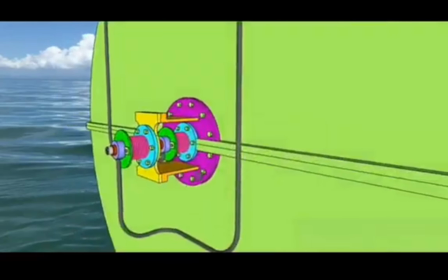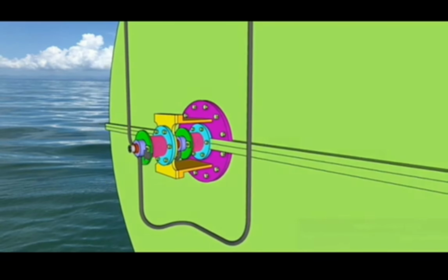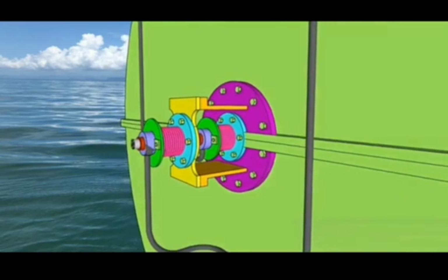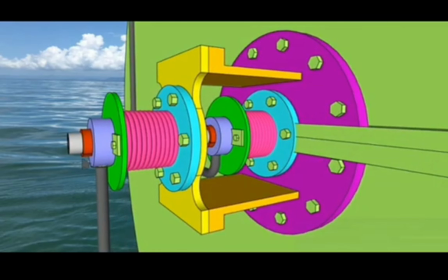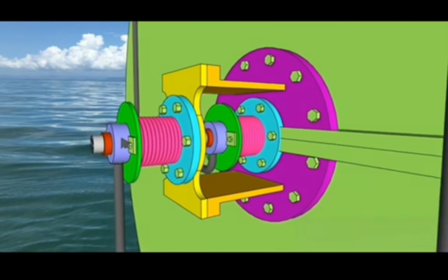And these are another two encoders, the main encoders, fitted forward of the engine. There are two given for redundancy. The first one is encoder A, and the second one, the outer one, is called encoder B. Encoder A is fitted exactly on number 1 TDC, taking its reference from number 1 TDC, and the second one is 45-degree offset from number 1 TDC. They are fitted that way, and in a few minutes I will explain why this offset is required. This is the setup they have given.